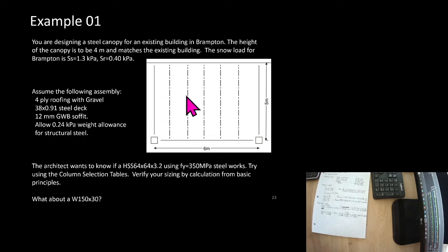So the tributary area, if this was a table, you guys would intuitively know that if I spread a load all over this, a quarter of it is going to go here, a quarter of it's going to go here, and depending on how the support was, if there was columns here, a quarter would go to each of those. It looks like the framing might mean that there's actually a uniformly distributed line load on this element back here. But we understand that these are each taking a quarter of the load.